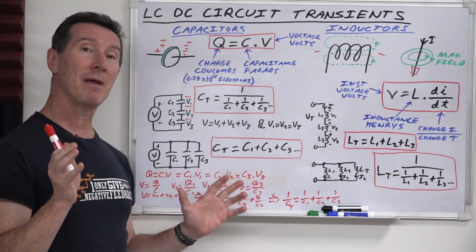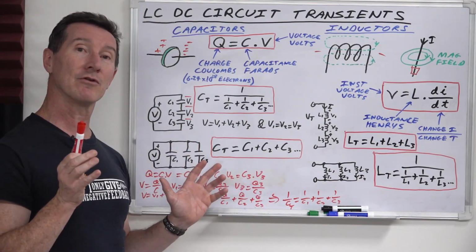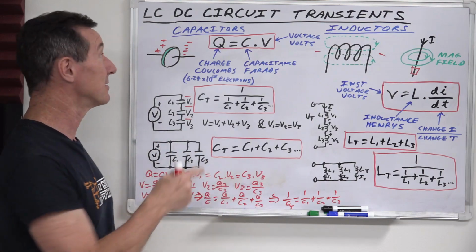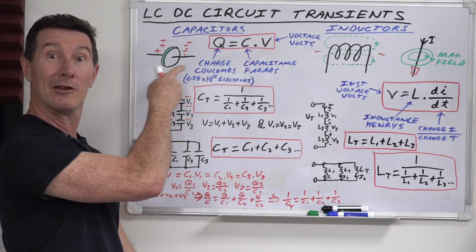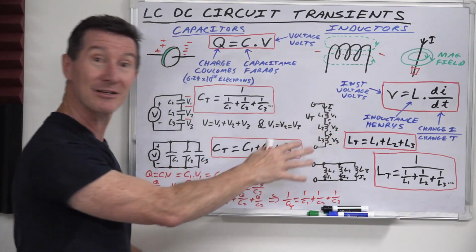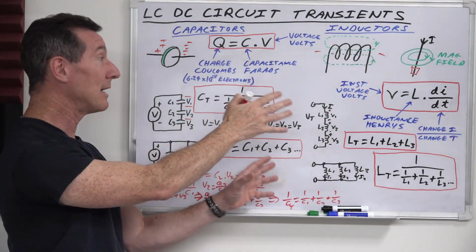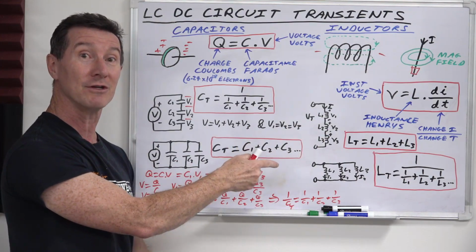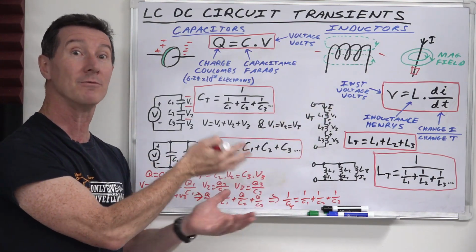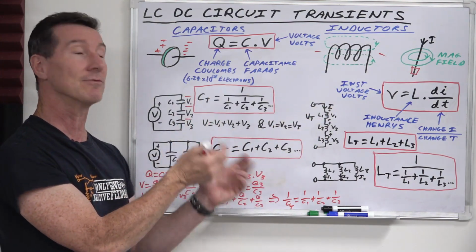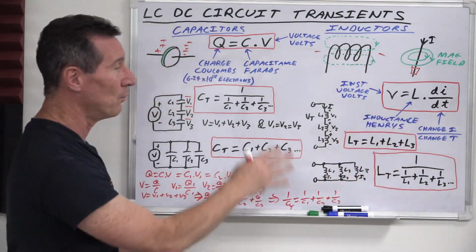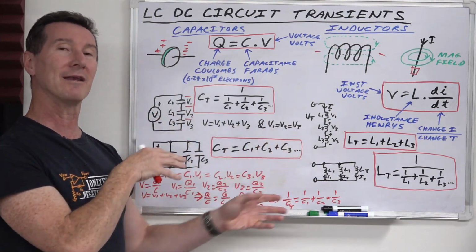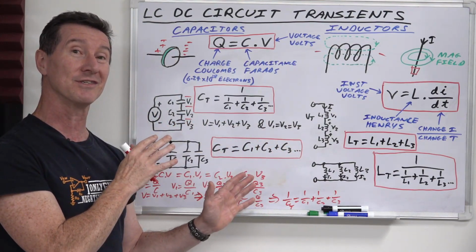So if you simply remember your resistance parallel and series formulas, you'll know that capacitors are opposite because they're not resistors. They're an open circuit, whereas inductors are basically the same as resistors, because measure an inductor at DC and it's practically 0 ohms because it's just a piece of wire. So the formulas work out the same, except your inductors can store a magnetic field and your pure resistances can't.